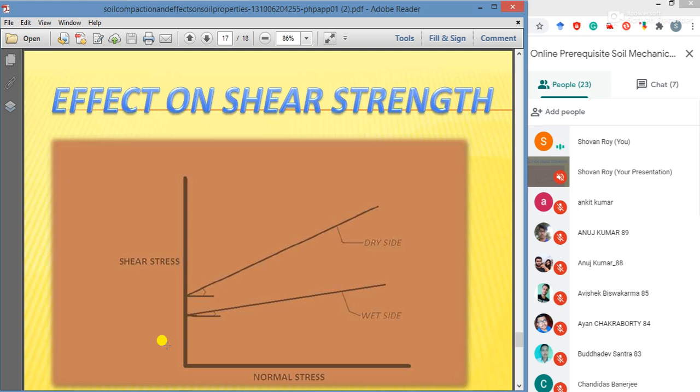However, at higher strains, the flocculated structure of the sample compacted on the dry side is broken, giving rise to the same ultimate strength for both samples. The manner of compaction also influences the strength of soil sample compacted wet of optimum. It is interesting to note that the clay cores in earth dams are usually compacted wet of optimum to tolerate large settlements without cracking.